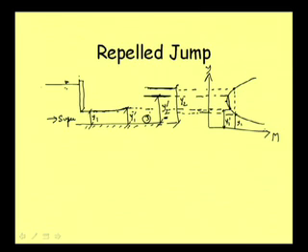Once it reaches this y1 dash as a supercritical flow, with the critical depth corresponding to this one, we get the sequent depth of the tailwater, which is the actually existing depth at the downstream point, and then it can jump, because we know that from this depth, if it jumps, only then will it reach this point.